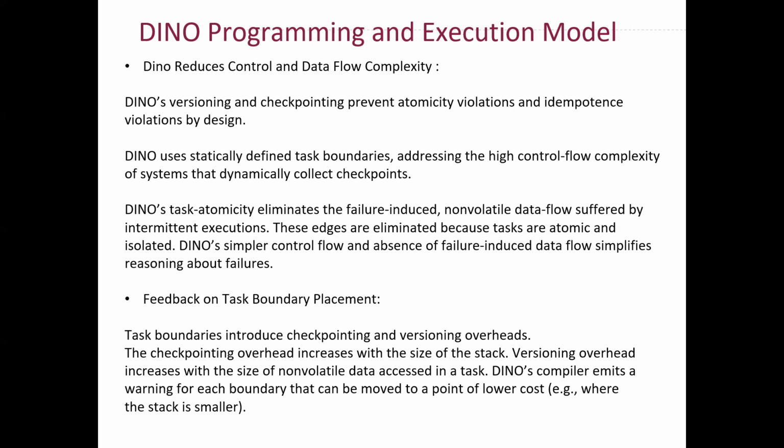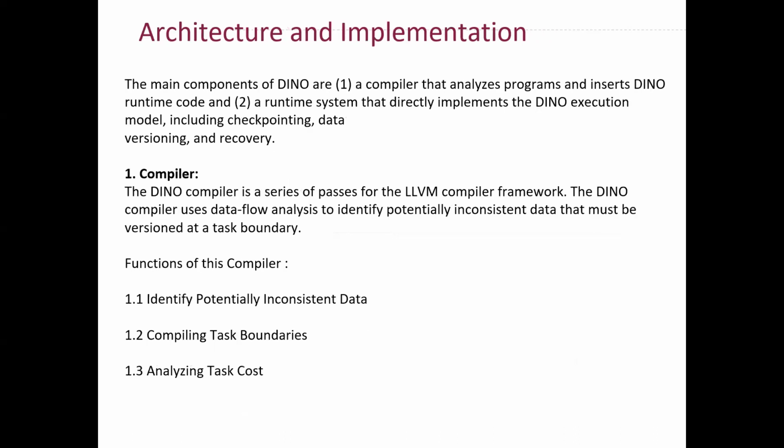Now, this might be either an input from an ADC or an input from a button or audio input or anything. This suggests that programmers try to construct task boundaries as close as possible around this access. And so all of this is just an effort to make the program as idempotent as possible.